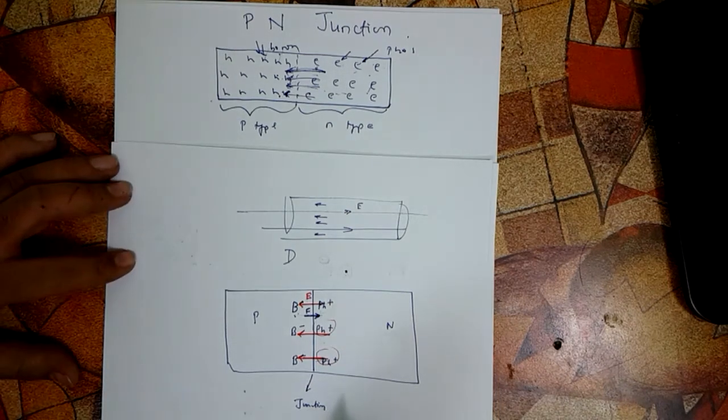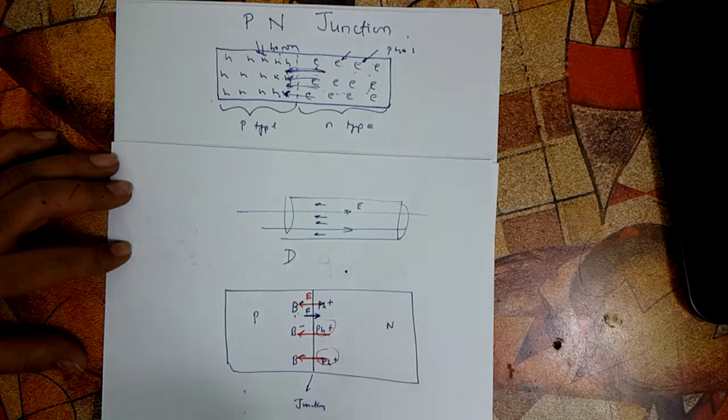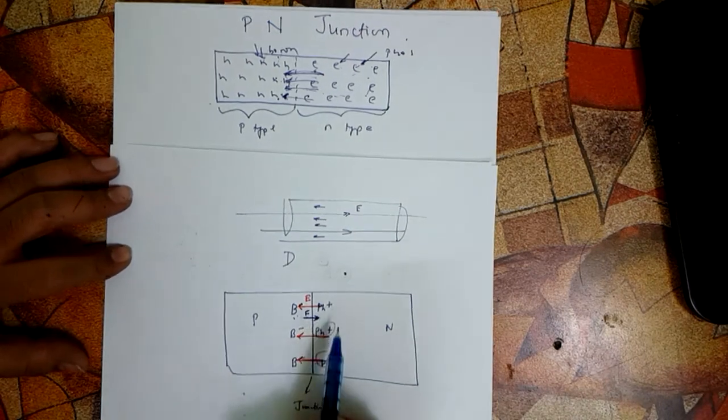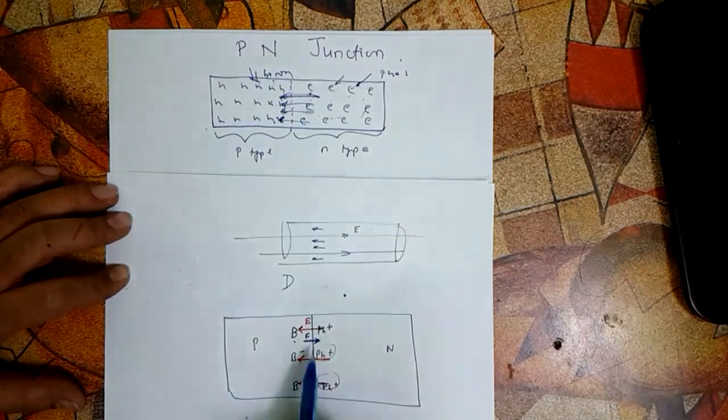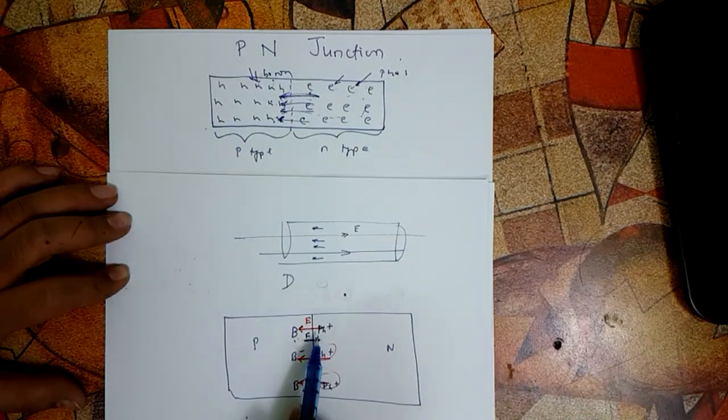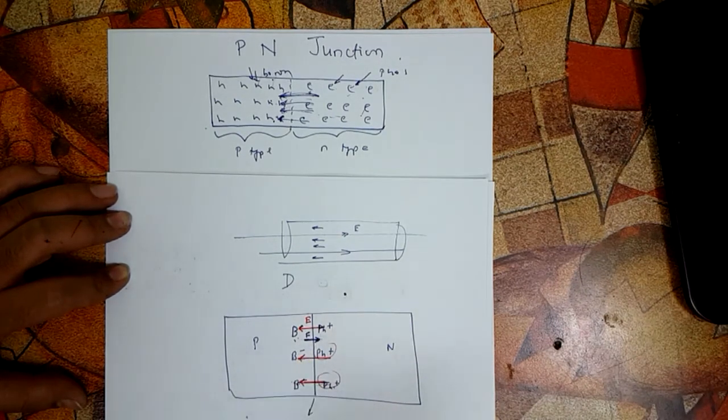Alright, so yeah, sorry for the disturbance. Moving ahead now. So as we were discussing, this electron would like to diffuse here, but this electric field which has been generated, obviously if the electron leaves here, positive charge, electron goes here, negative charge, so already lots and lots of negative charge, lots and lots of positive charge. So positive and negative will produce an electric field towards left, and this electric field will produce a force on the electron towards right. So we know that because of this force, what will happen? Well, the electrons will start to move in the opposite direction.